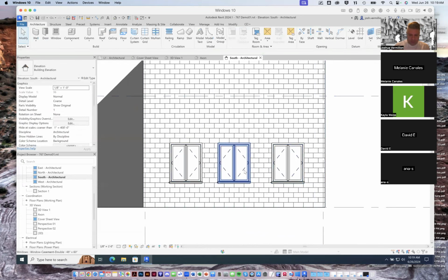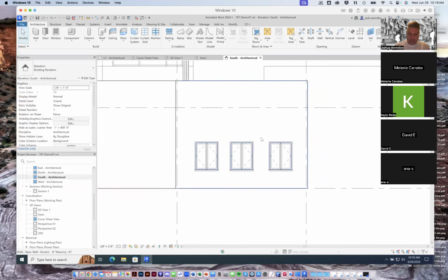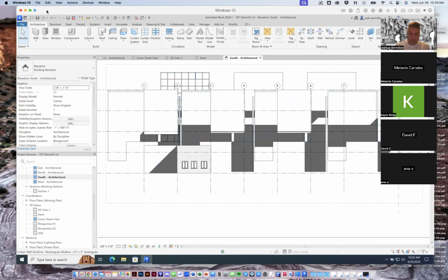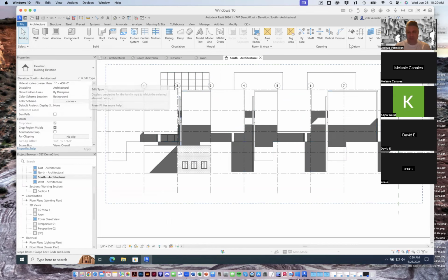Now, again, I wouldn't necessarily consider these great windows at all. So let me just show you an example where I started making my own custom windows. Again, it talks to the level of parametric capabilities of Revit. When you're using things like windows, there are families of windows, and you can go back in at the properties level, at the type level, and then at the family level to start to change things, depending on how far back into the first principles you want to go.